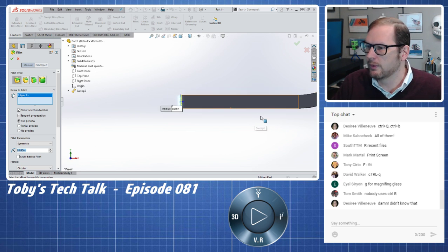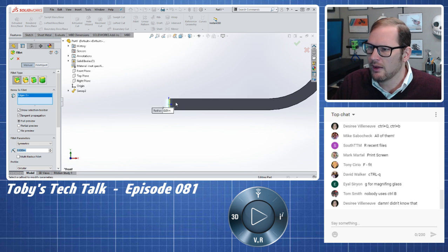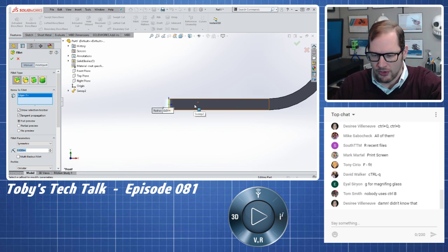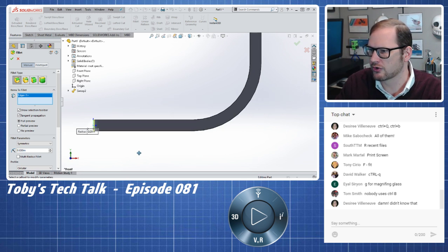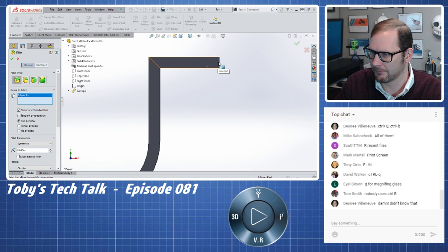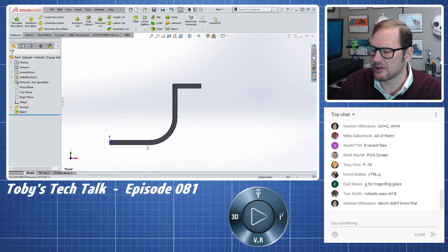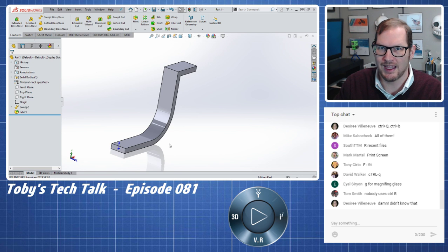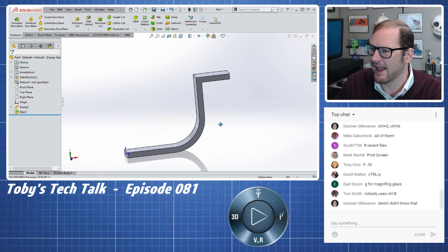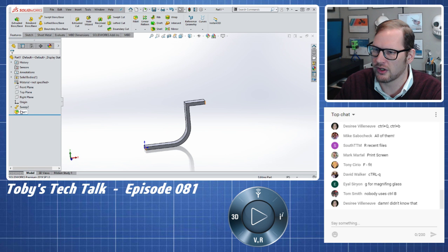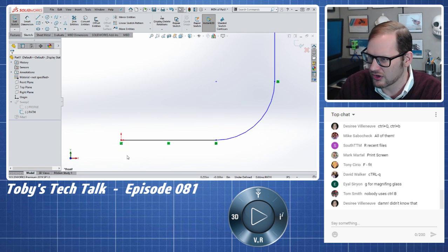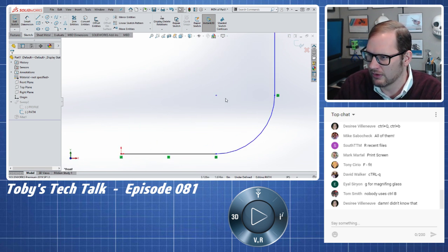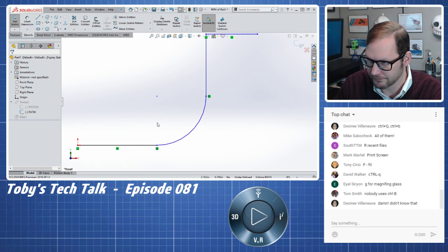A lot of times what we would do is zoom all the way out and then zoom back in there. But SolidWorks actually has a pan command, and what it is, you hold down the control key and then you press down on the wheel on your mouse. So you hold down the control key and press down on the wheel on your mouse, and that lets you pan. I actually used that just a few moments ago without even really thinking about it because I just needed to move my sketch down into a different location. That's another spot where I use that a lot. You're working on a sketch and you need to relocate how you're looking at that sketch. So, you may move that sketch over, something like that.